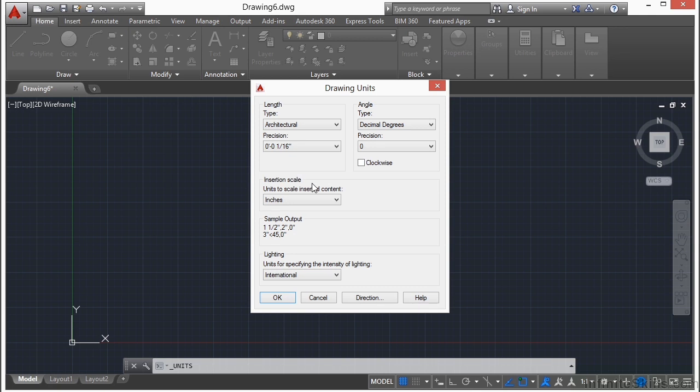Now, it's smart enough to know that 12 inches is a foot and will display your object as being 1 foot, 0 inches long. And when you're entering in objects to specific lengths for architecture, you can tell it to be 2 feet, 0 inches, or you can type in 24 inches. So keep that in mind. Architectural format will display fractions of an inch in fraction form, while the engineering setting displays them in decimals of an inch.